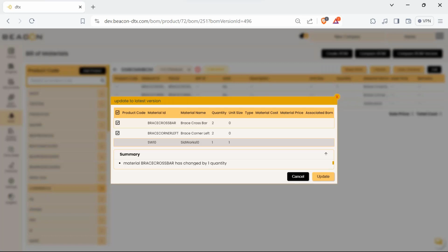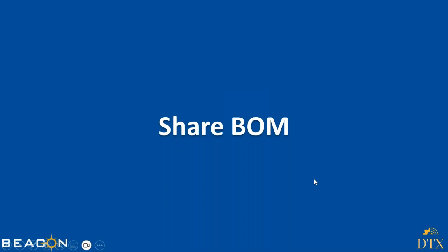With the connection between the variants, whenever the E-BOM or the design BOM gets modified, the other challenge of updating all the variants, or all the places wherever the BOM is materialized, becomes easy with this update option. With just a single click of a button and the option to select which components to update, the update happens automatically, and there is a version history also to always track how things have gone.